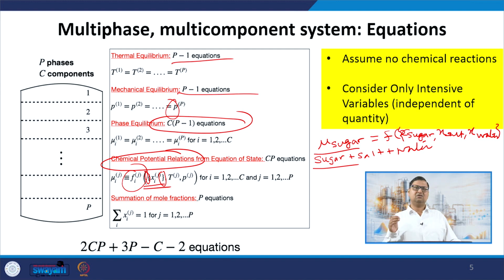But I again want to emphasize to you that if your process calculation or process simulation is going wrong in anything that you are doing, the main culprit which I would expect is the equation of state that you are using. If, for example, you are doing everything perfectly, but you assumed an ideal gas law for water and sugar or any complicated system like wastewater, then I can say without any hesitation that whatever you have done is wrong.